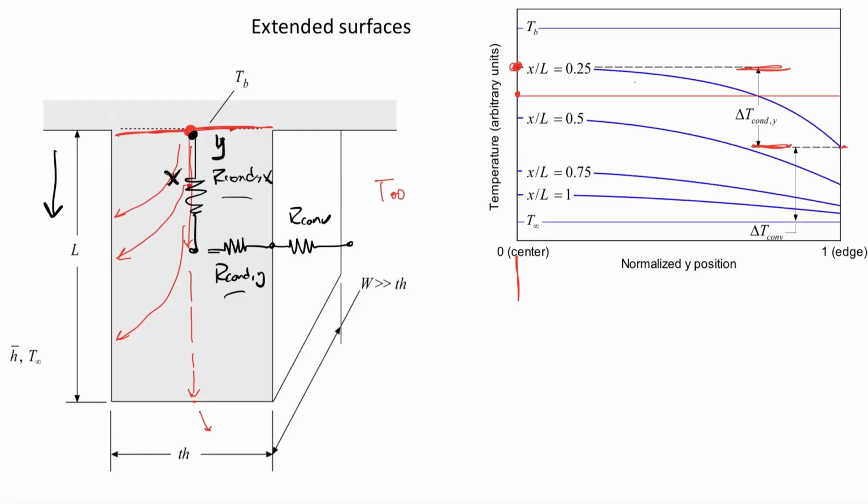Okay, so how do we actually decide what's good enough, right? If there's going to be heat flow, there has to be a temperature gradient. So you'd never have a perfectly level temperature profile like that. But what would be good enough? What is the criteria that we can use to decide if a 1D approximation is a good approximation or not? So we would want to look at the resistance ratio, or the ratio of resistances in the direction that's sort of that second direction.